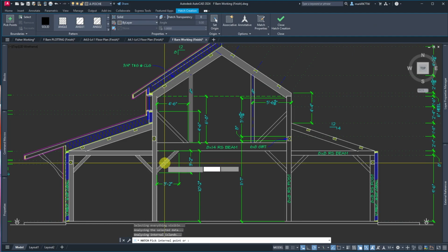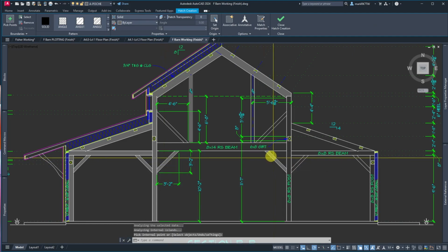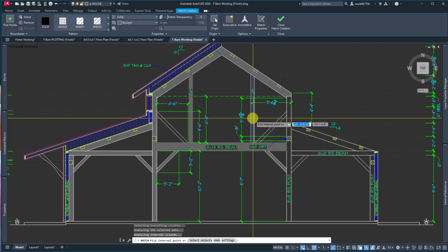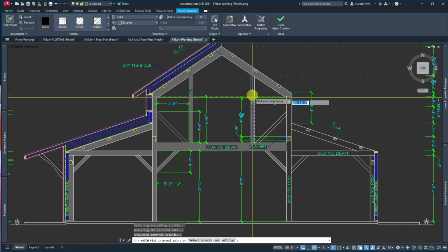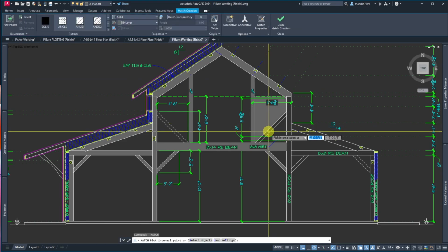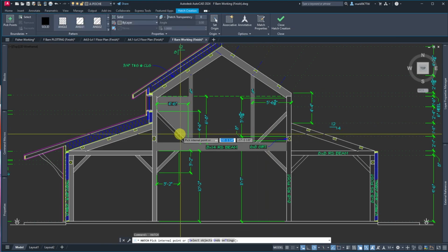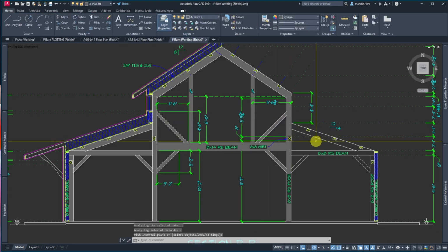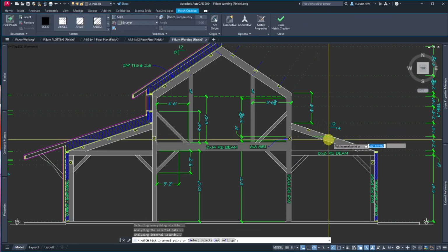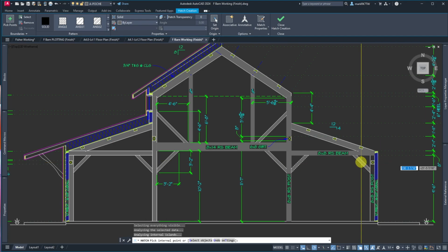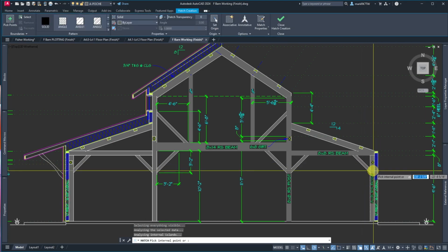Then let's hatch our knee braces, and then let's hatch our horizontal, and then let's hatch that. Come to the other side, get it, and then up here and up here. And we've got that. Then we can do this knee brace, and I'll do this knee brace separately. I'm just hitting enter, enter, enter, enter. Then that, enter, enter. This, no little piece. Enter, enter, this, enter, enter. Knee braces, 1, 2, enter, enter, and the final post.